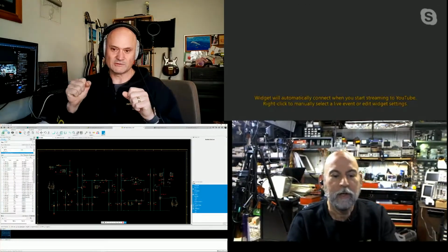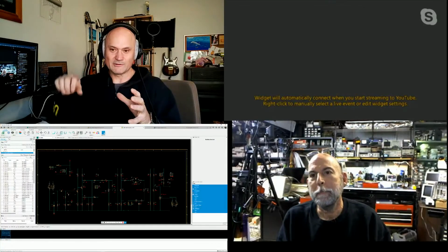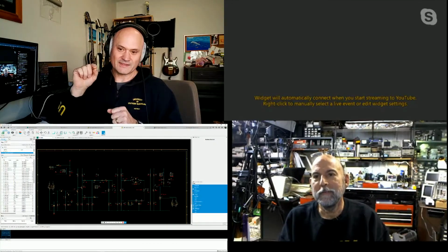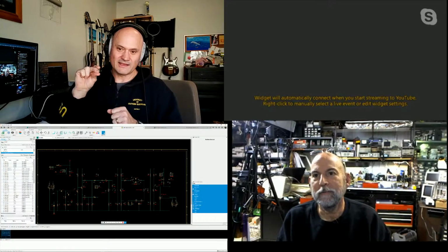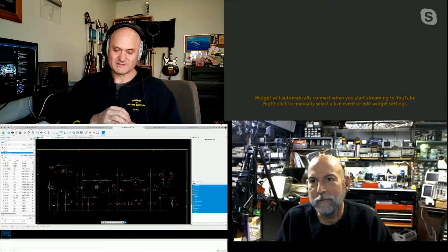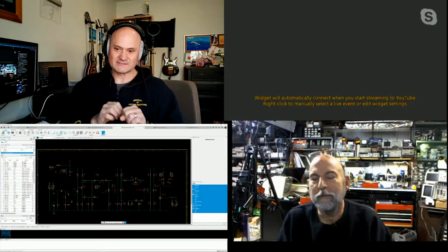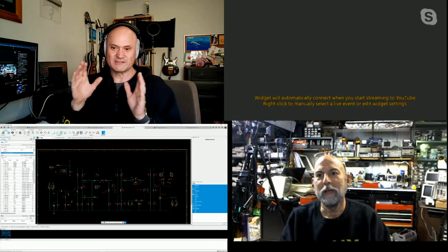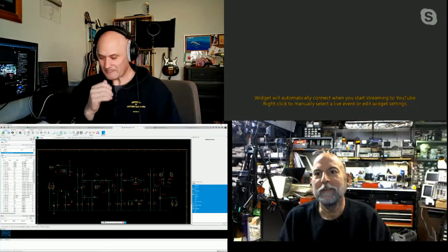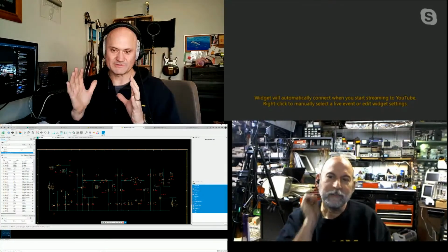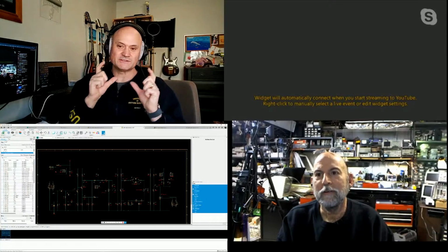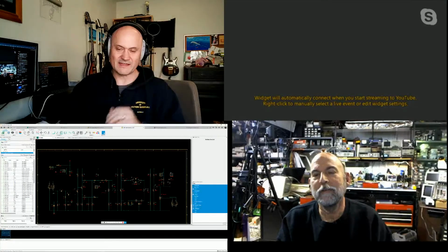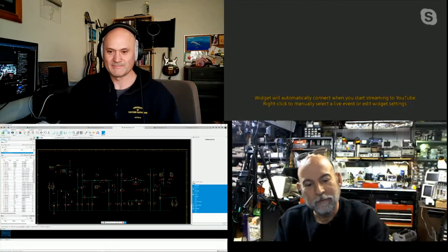And so what you do is you get a real amplifier with a real microphone in a real room, and you record an impulse response. So you send an input to the amp that's just like a step pulse, and then you capture and digitize the output of that, and that becomes an impulse response. That becomes your coefficients for an FIR filter, and that FIR filter then gives you the sound of that whole amp, mic, room setup. And it's very accurate.